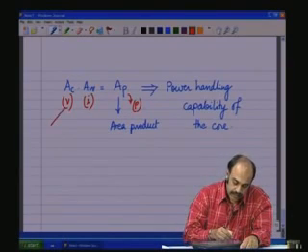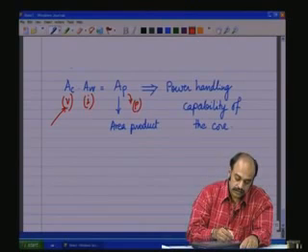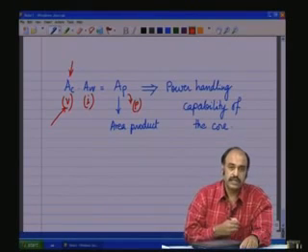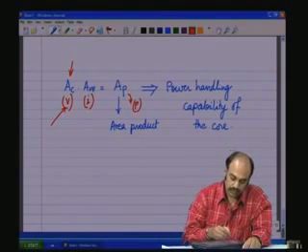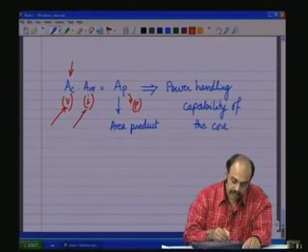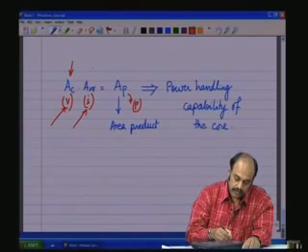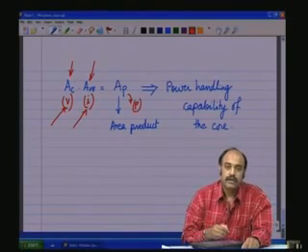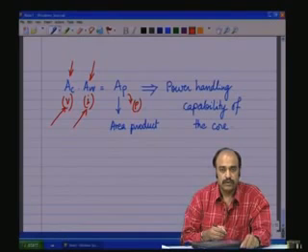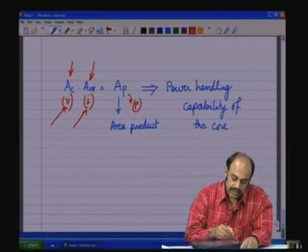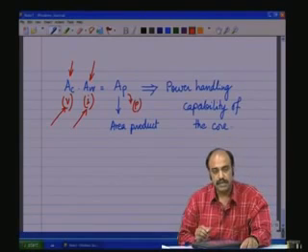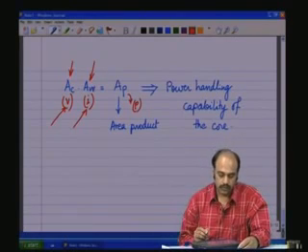This is the electrical parameter which is trying to map to the physical dimensional parameter of the core called the cross sectional area of the core. Another electrical parameter, the current, RMS current, which is trying to map to the window area of the core, another physical dimensional quantity of the core. AC, AW and sometimes AP are given in the data sheets of the core.